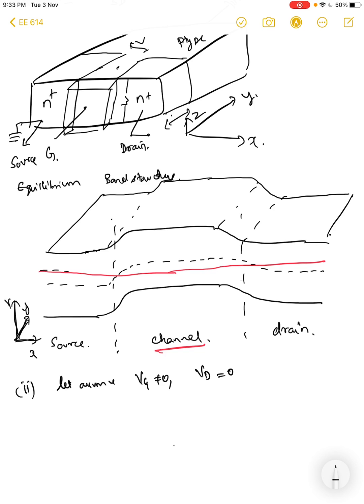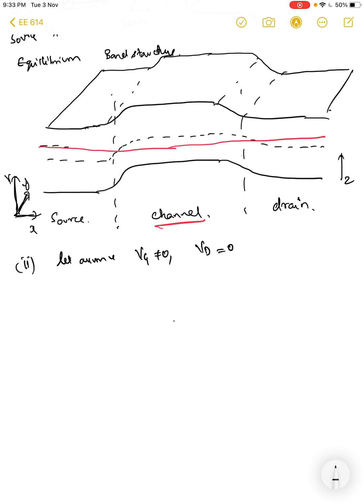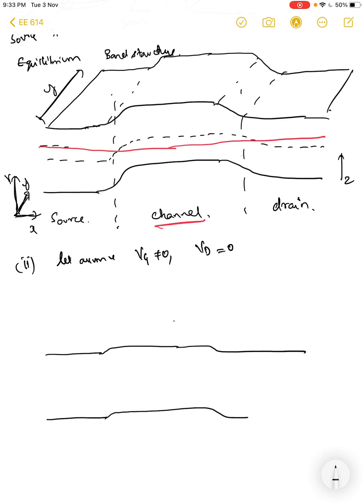Once again, I want to remind you that whatever you see in the z axis is not the thickness, but just the potential landscape. So now let me draw this again. We have a source, and so basically this is y. At this particular point it is the surface, and when we invert the channel, you create an electron concentration at the surface. So the surface now becomes a little less p, but a little bit away from the surface, it will again change.